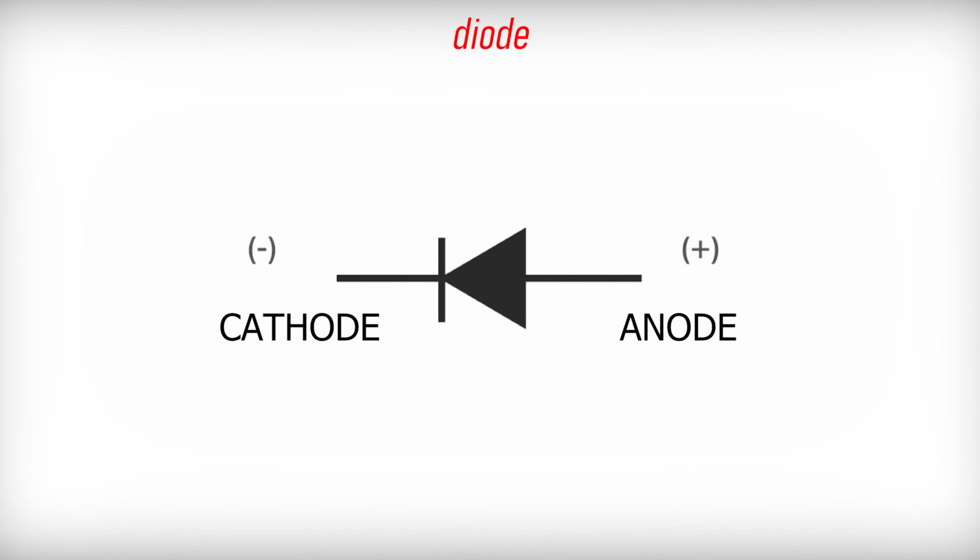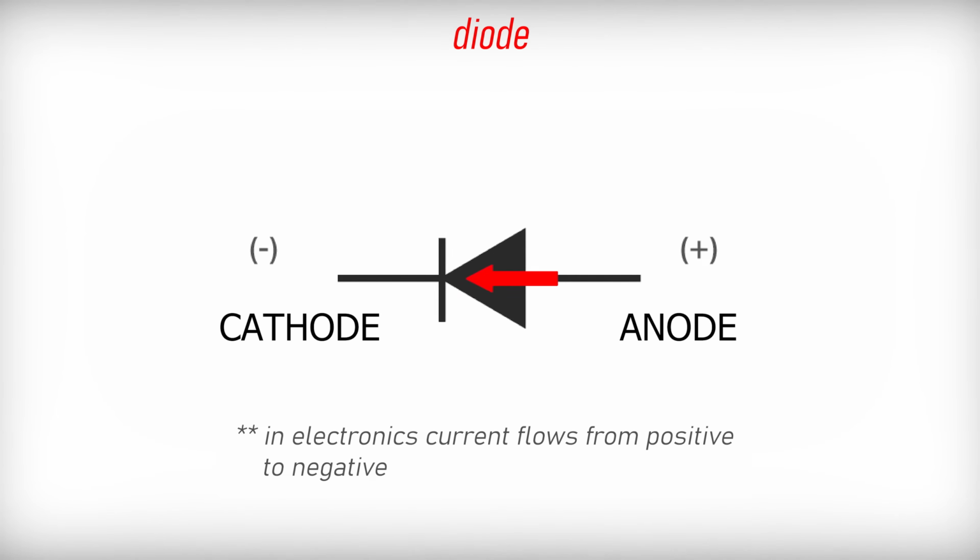The symbol for a diode in a circuit diagram is a triangle pointing toward a straight line perpendicular to the wire. The orientation of the triangle indicates the direction in which current is permitted. The electrode marked with a triangle is called anode, and the one with the line, cathode. The current flows in from an outside circuit through anode and flows out through cathode.